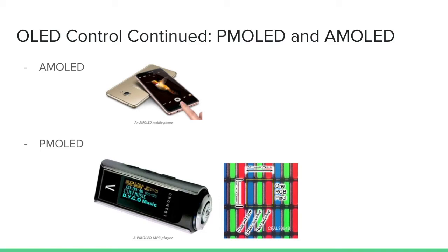AMOLED is the other type, or active matrix OLED. It is also associated with an addressing scheme. For a rows times column display, to address the display in rows plus columns, unique addresses are used. Row is selected with a signal VR, and columns are selected individually with a VC in order to turn pixels on. Color PMOLED works similarly, but there are more OLEDs in a single pixel leading to wider rows.